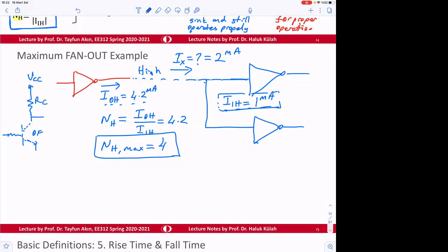So what is this voltage? VCC, right? So let's say VCC is 5 volt. My voltage is 5 volt. And then this is connected to the next gate, and the next gate is going to be like this, right? And then this is going to be in saturation, so that output is going to be 0.2 volts. So this is going to be 5 initially. Correct? So there's going to be a current needed here.